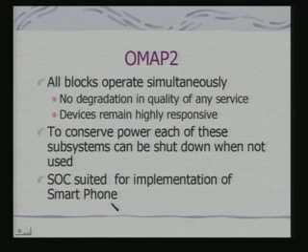So, all blocks here operate simultaneously. So, there is obviously no degradation in quality of any service. Why would the degradation come in? If that service is being shared on a single processor, then depending on the load, the time allotment on these different services can vary. A simple example is, if the processor is loaded, then there may be a situation where a video decoder may miss a deadline.